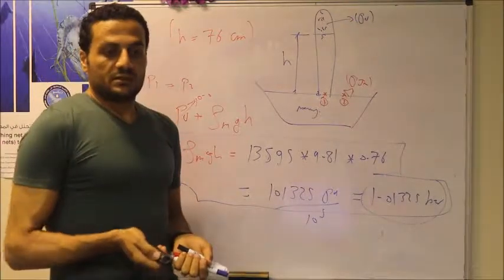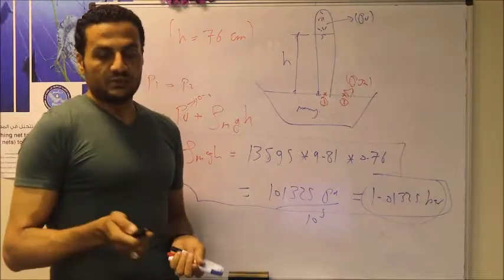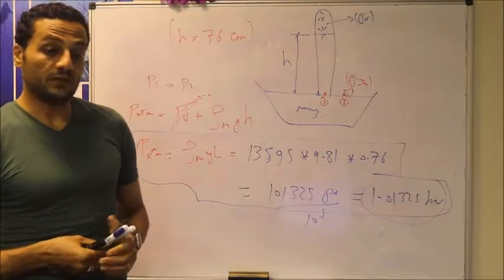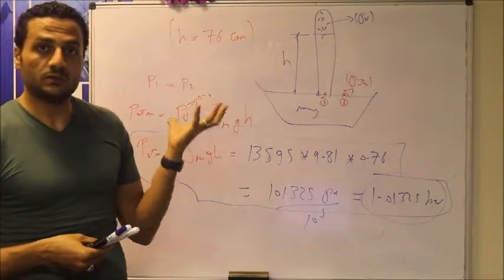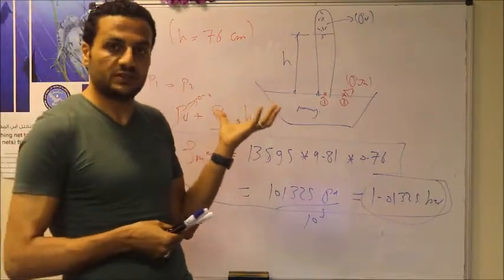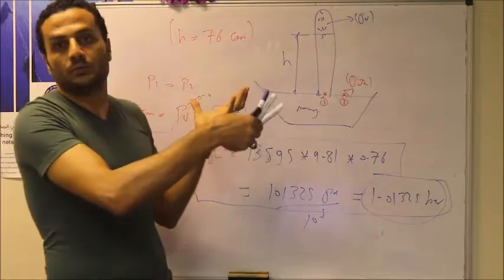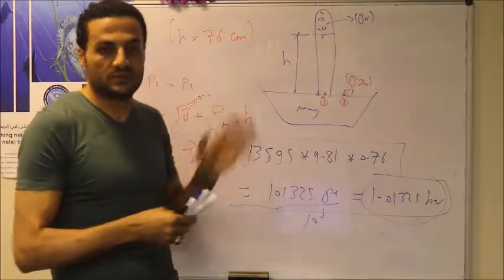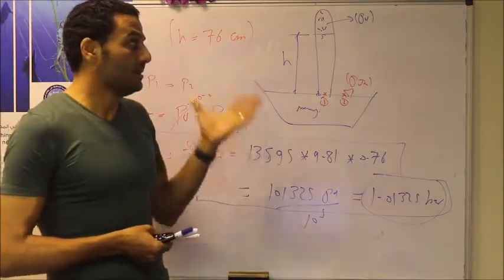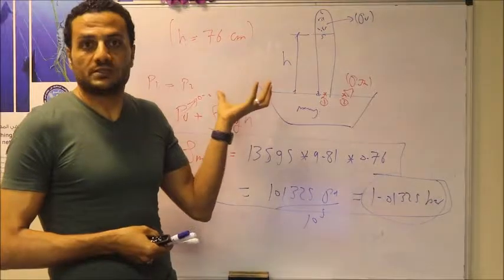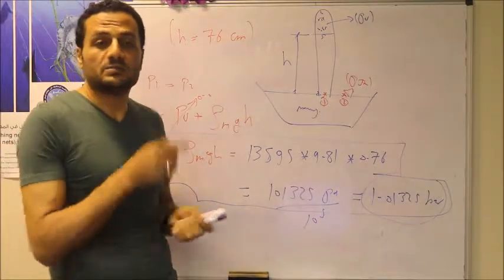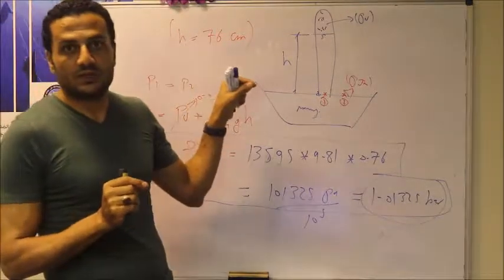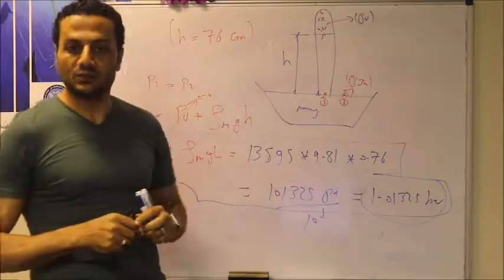In the last slide, you can see an example. You can just go through this example. In some cases, if the pressure is high, and I want to measure the pressure of a gas in a tank, then we can consider a U-tube manometer. Inside this U-tube manometer, we put a manometer fluid and then measure h to measure this pressure. But if the pressure inside this tank is very high, one manometer fluid may not be able to withstand this pressure. So in this case, we can add another manometer fluid.